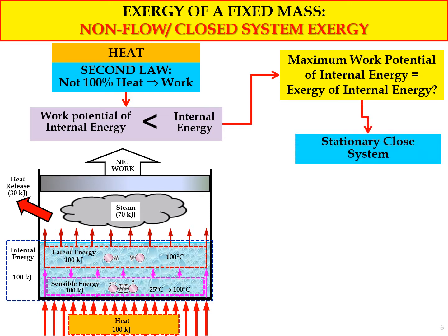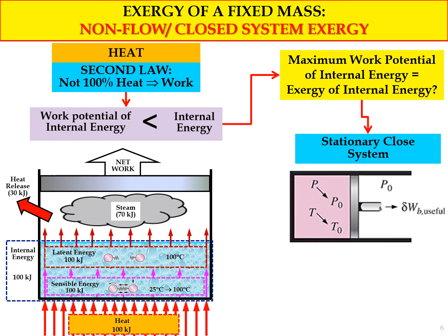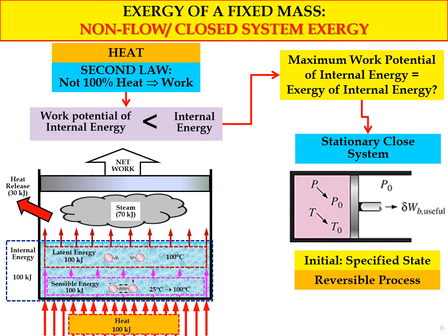Okay, so let's consider a stationary closed system, something like this, a piston cylinder device again, and the condition inside of it is at a certain pressure and temperature, P and T, and it will move to the atmospheric pressure equilibrium, which is P naught and T naught, and it will generate useful work. So the initial state is a specified state, and also this is a reversible process, and we assume that the final state is the environment state. So this is the exergy definition.